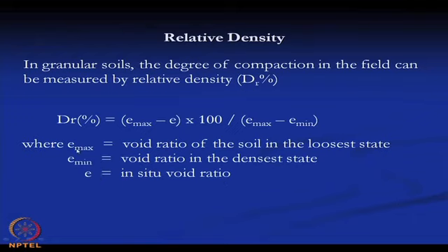So, if we know e max, e min and e at any condition, then we can determine the degree of relative density of the soil at that situation.